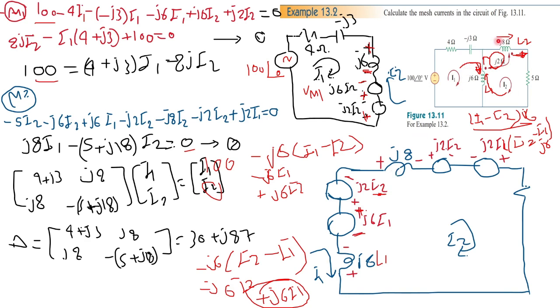Then I2 would pass through L2 causing a voltage drop, positive here, negative here. And then as we said, it is an aiding connection with regard to I2 passing through L1 and L2. So the mutually induced voltage on L2 because of I2 passing through L1 would be positive here and negative here. It's an aiding connection, so this voltage has the same polarity as this voltage drop.